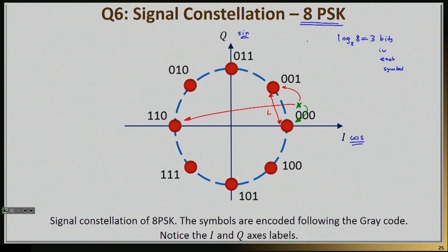And that's the value of this type of graphic representation: the minute you see one of those diagrams, you can immediately make a decision about the tolerance of that system to noise. Similarly, you can decide whether one modulation scheme is better than another. For example, if I compare this diagram with a single BPSK, in BPSK, remember, I have only 2 symbols right here.